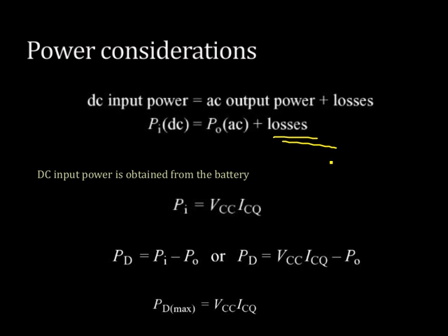Okay, so as the collector current and voltage change, as you have larger collector current, these losses will increase in the power amplifier. Now the input power is VCC into ICQ. What is ICQ? The quiescent collector current. So if you consider an amplifier without any distortion, then PI will be equal to VCC into ICQ, the quiescent collector current supplied from the battery, the average collector current.